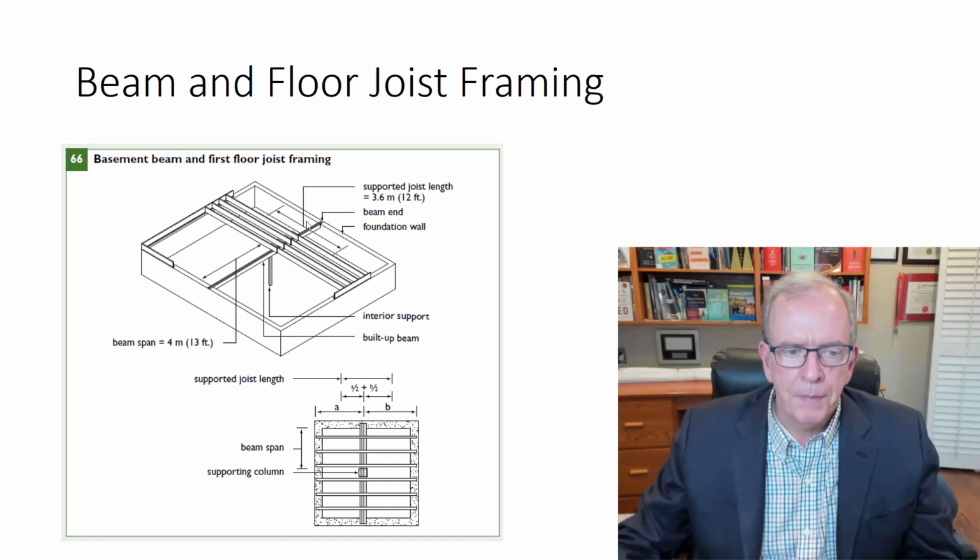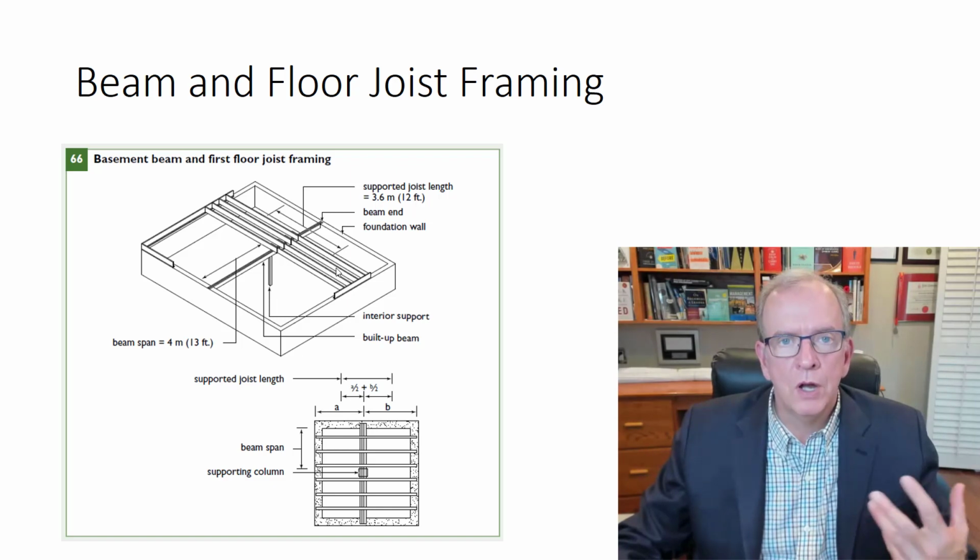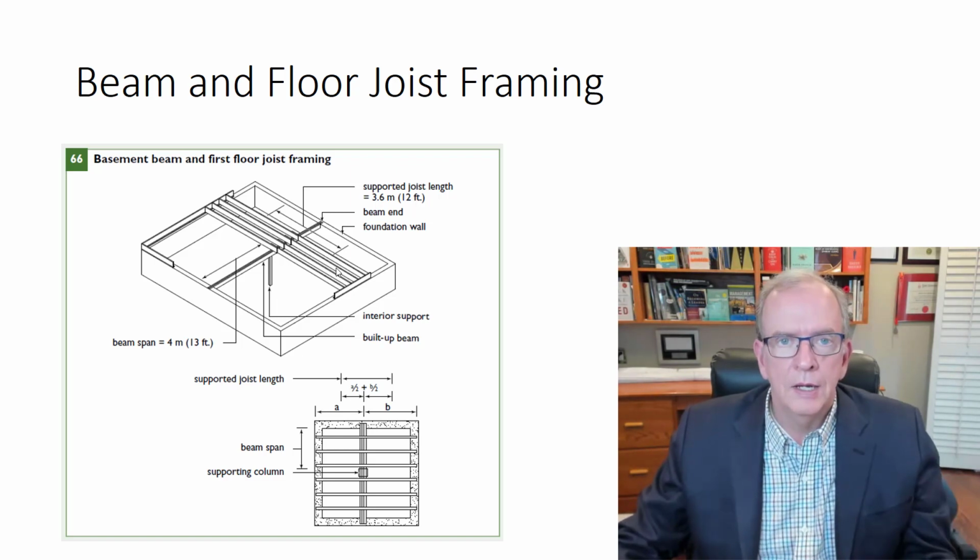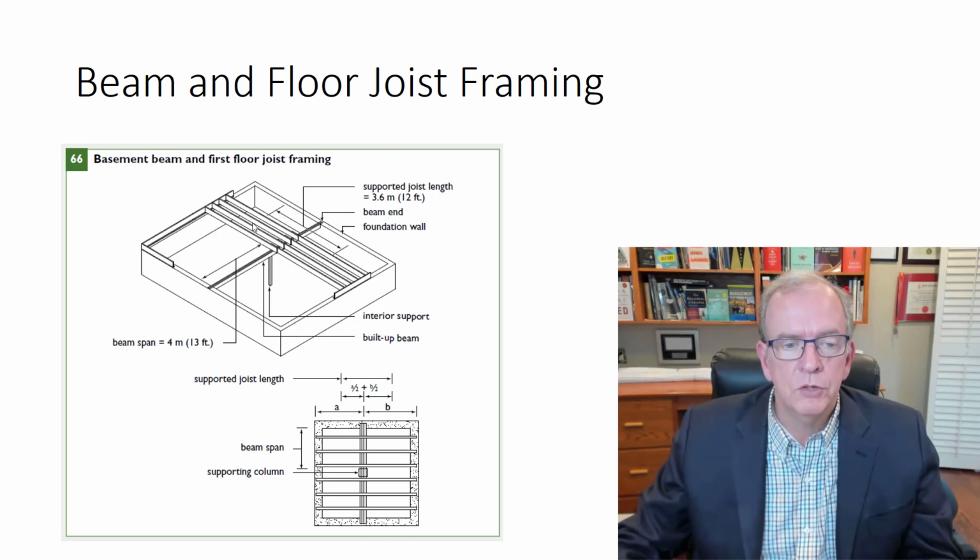So we'll start to talk about what are some of the things that you need to know. Well, in a basement foundation, you've got floor joists. Now, these are representing what we call dimensional lumber floor joists, and that's made out of solid lumber. May not be the most common right now. I would say manufactured joists are much more prevalent, at least in the area that I'm in, Greater Toronto area, but other cities in North America you probably find similar. But there might be some jurisdictions where this is the prevalent material that's used. So it just depends. But dimensional lumber for decades and decades has been very popular. If you're working in renovations, any house that's probably older than 15, 20 years, you're probably going to run into dimensional lumber from that perspective.